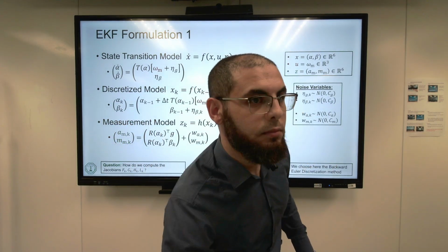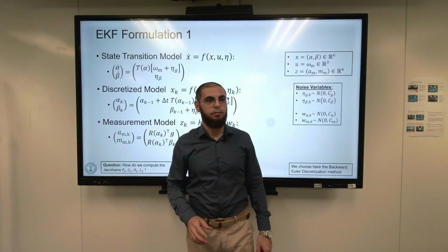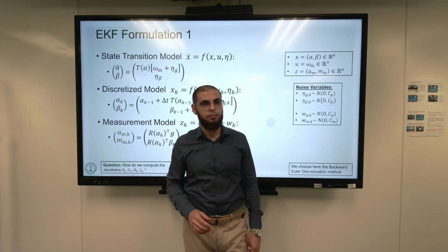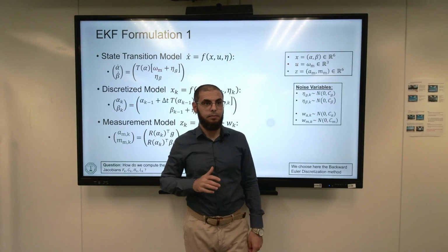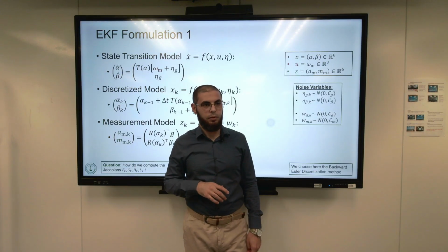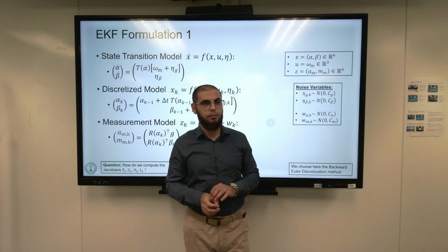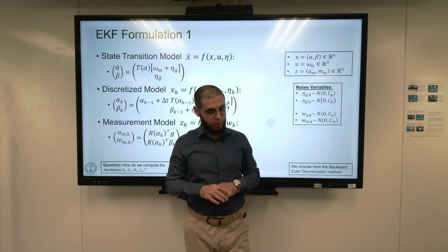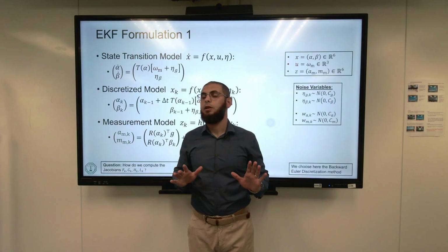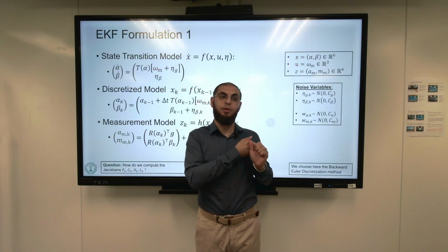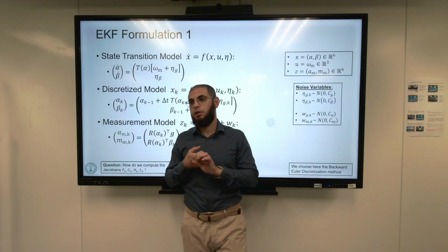I think it depends on the application. For example, in the aircraft, we have 2 types of response, one that requires slow response but accurate, like the altitude, the heading. It's okay to be slow, but it has to be accurate. So we take the second formulation. But like roll and pitch, I think the first is better for stability. That's a good point, depending on the application. But that's related to the speed. The accuracy is another problem.